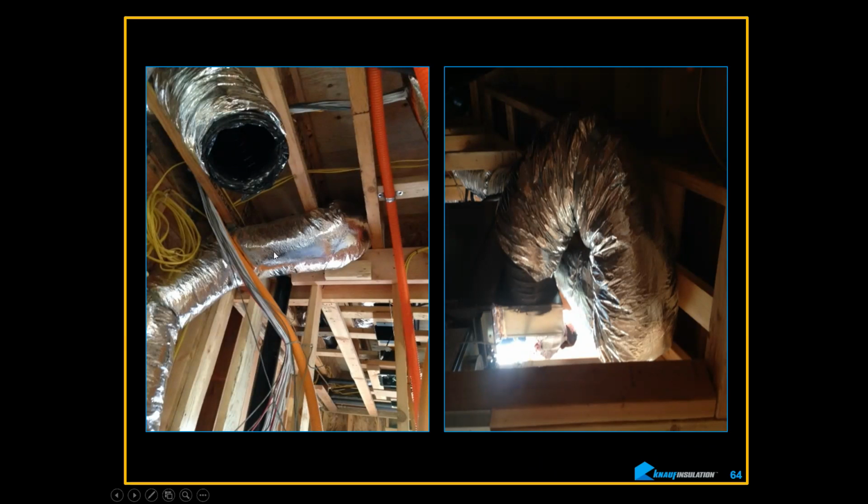You probably just added 20 feet to this length, plus this, maybe another 10 feet or more. So this 4-foot section here is now equivalent to 30 feet long for pressure losses and flow rate drops. It's unbelievable. And this is done all the time. This is a $4 million house in California. Same house right here. It's unbelievable.